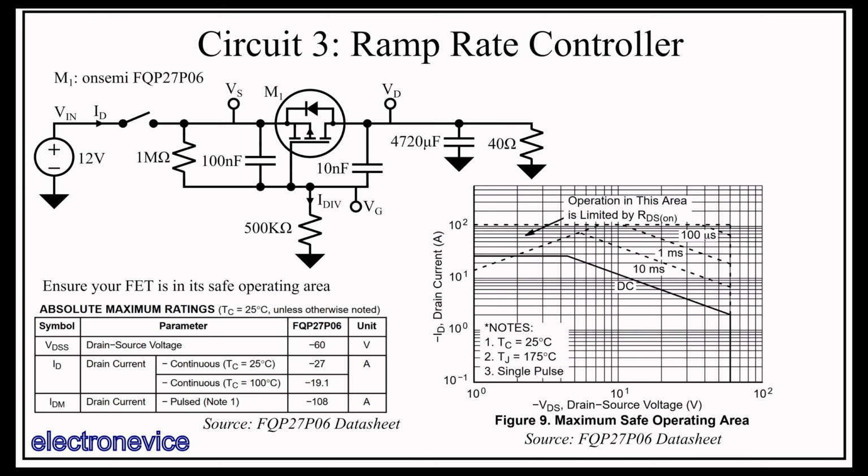You can sort of roughly interpolate between the curves if you have different durations, though it's best to make conservative estimates when you can and just get a bigger MOSFET if you really need a bigger current spike.